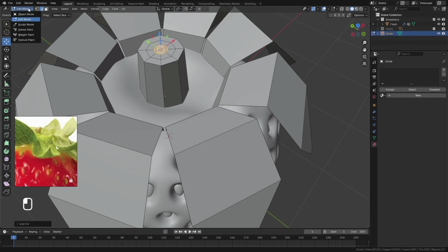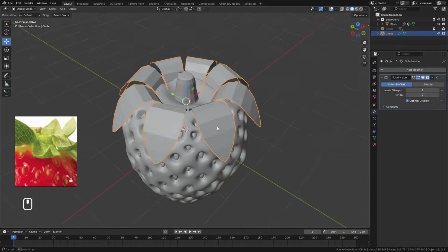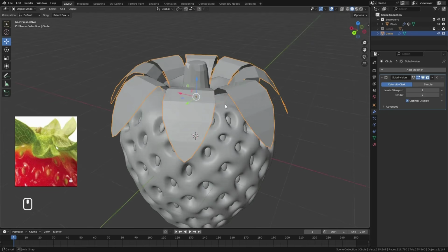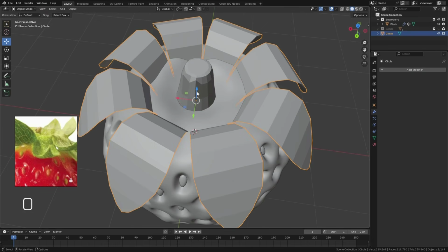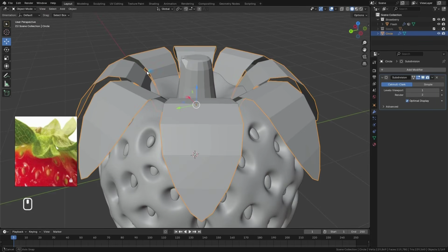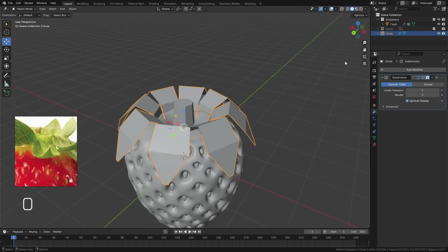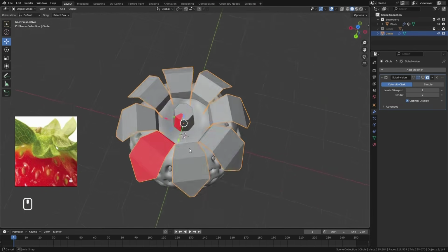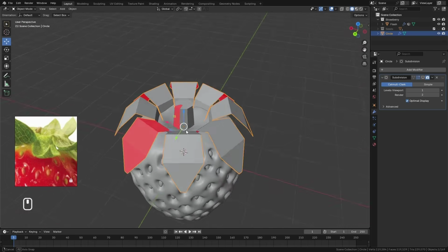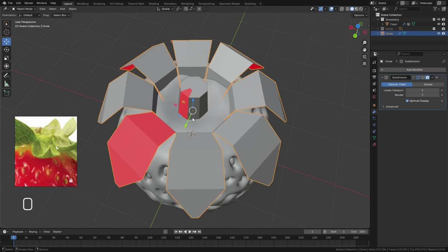And let's go back to the object mode. This is material, so let's go to the modifiers. Add one level of subdivision. It's already a bit more pleasant to look at. So let's go to the subdivision, apply it, and we have some problem here. Why is that? What the hell is this? This is due to inverted normals. So if I go to the viewport overlays and enable the face orientation, you see we have some flipped normals.